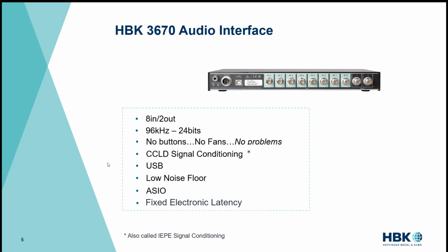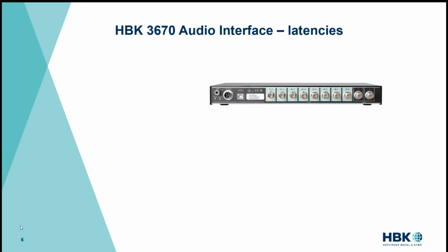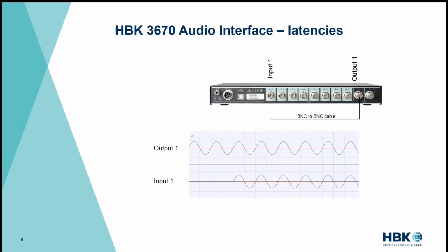It has a USB interface, low noise floor, an ASIO driver, and the team in Europe worked very hard to have a fixed latency between the input and the output on this device. Let me explain what we mean by latencies. If you connect input 1 to output 1 of the 3670 with a BNC to BNC cable, and if you generate a sine wave, for example, you will notice a time delay between the two.